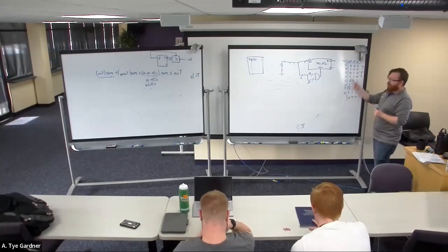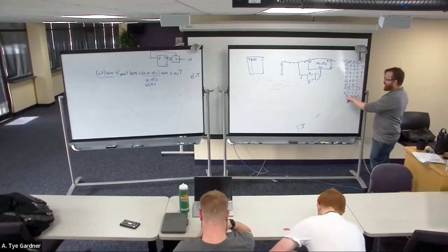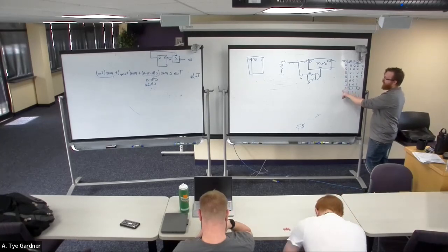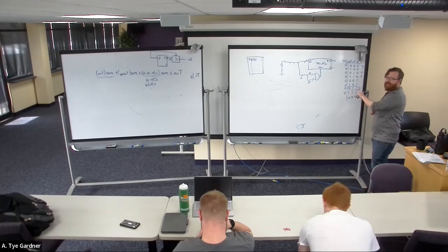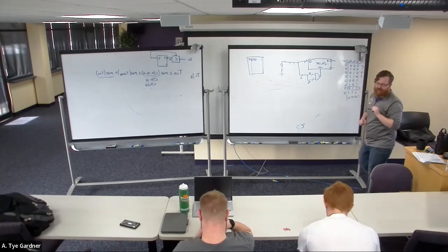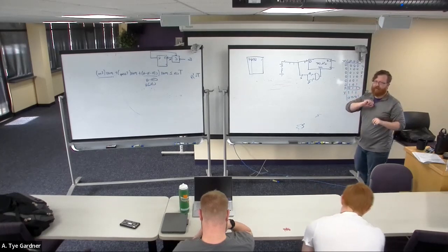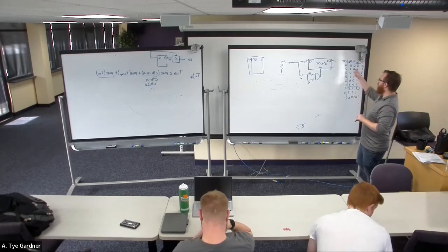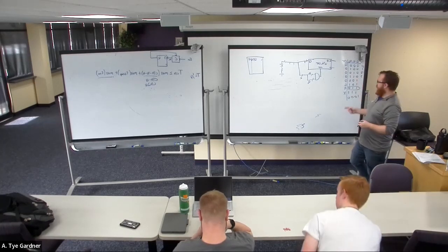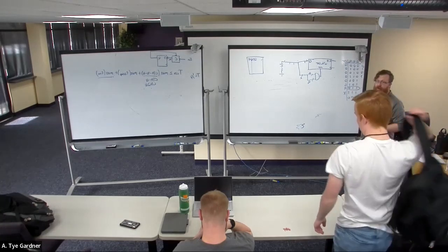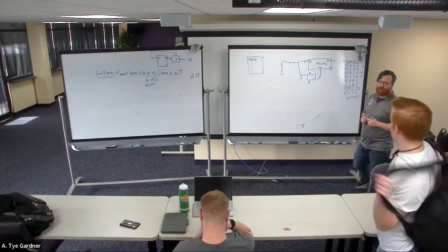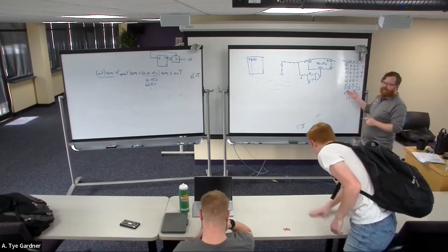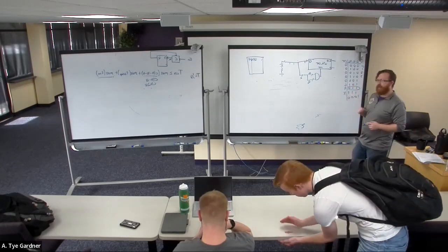And we could do that. We would find that out through the K-map because these two are going to be logically adjacent. So they're going to share an implicant, which means if I have a circle that encompasses 2, it drops 1 variable, and the variable that will be dropped is Q0. But as I said, we're going to be using K-maps as this logic gets more and more complicated. As it stands, I just don't need it, but you would get the right answer with the K-map from this truth table.